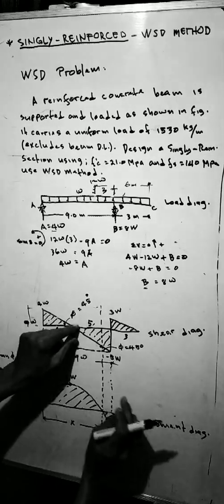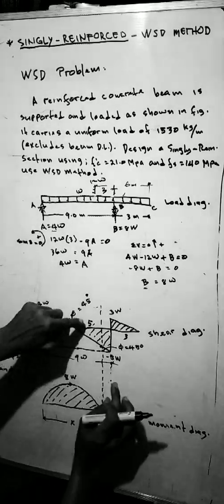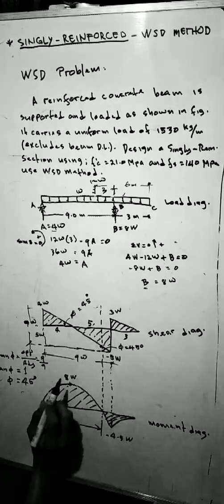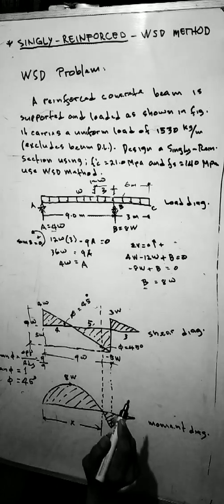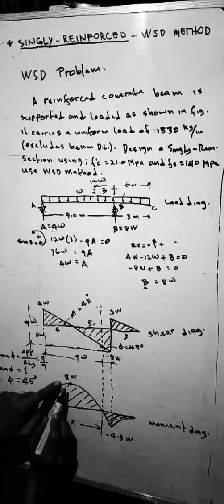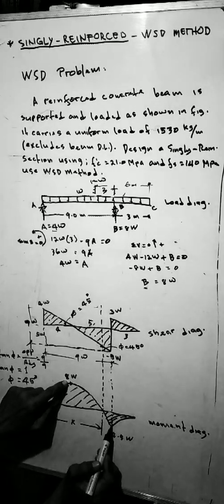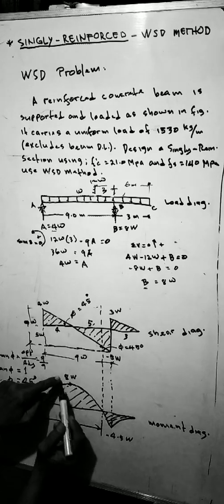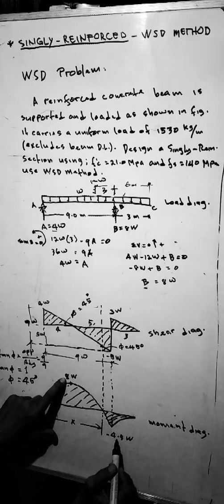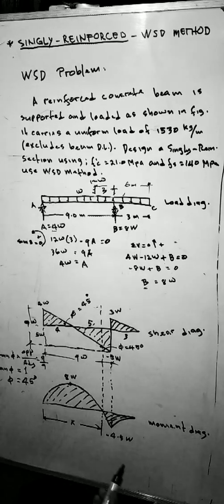Okay, then, this one is a negative area. The same procedure with this. 5 times 5 is 25. Divided by 2 is 12.5. 12.5 minus 8W. We draw the line here, up to here. So the remaining 12.5 minus 8 is 4.5W. This is negative.